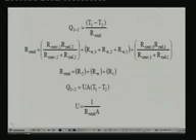So this is the mathematical form of whatever I have discussed just now. You can write for this multi-layered wall Q1 to 2, that means from room 1 to room 2, as T1 minus T2 divided by R total, where R total consists of these resistances. This is the equivalent resistance of the radiative and convective resistances in parallel for room 2, and this is for room 1, and this is the resistances in series for the wall, and this is the total resistance, and this is the heat transfer rate.